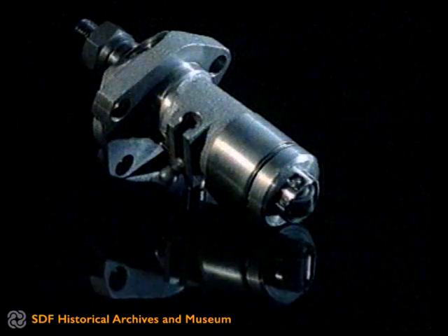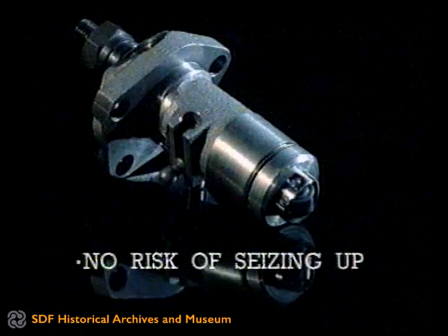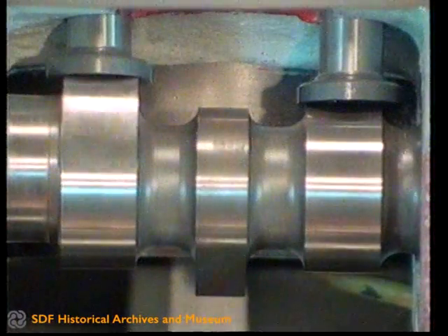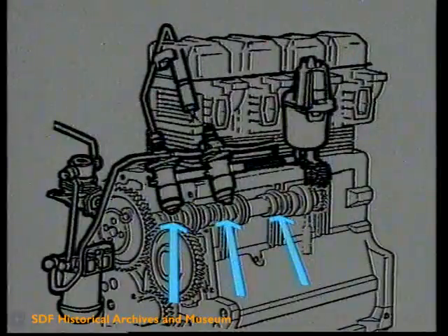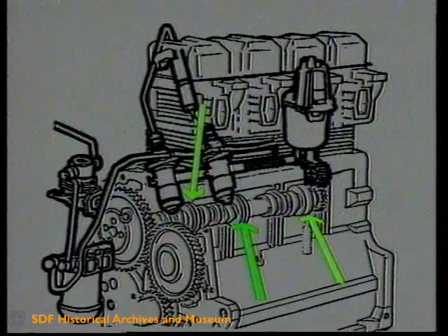Scarcely sensitive to any water possibly present in the fuel, hence no risk of seizing up. Each cylinder is fed from a single immersed pump actuated by the camshaft. This solution has contributed to the compactness of the engine length and to the uniform distribution of the load on the camshaft, by permitting also the insertion of two brackets for each of the main bearings, so as to reduce shaft bending to the minimum.